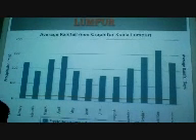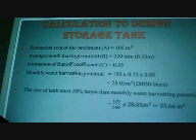Our group has considered the average rainfall in Kuala Lumpur because this building is located in Kuala Lumpur. Based on this graph, November has the most rainfall in Kuala Lumpur. So for the calculation to design the storage tank, we take the average rain in Kuala Lumpur in November to calculate the capacity of the tank that we can use for this rainwater harvesting.